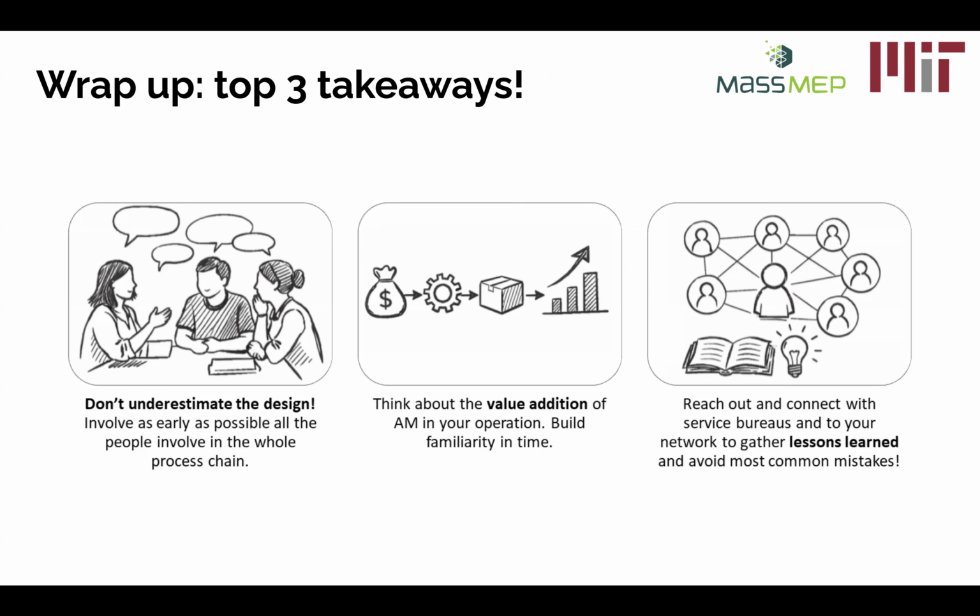To make sure that the part you're designing can actually be printed and post-processed, and that you have access to the cutting tools you intend to use, during the design phase you should involve as early as possible all the people who are experts of the different manufacturing steps of the process chain.